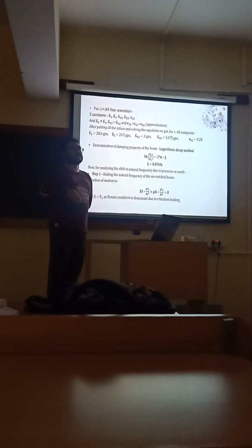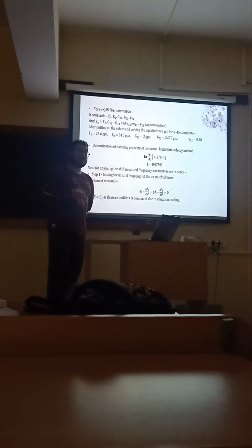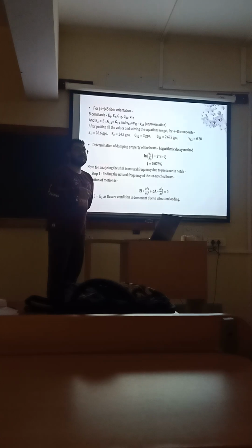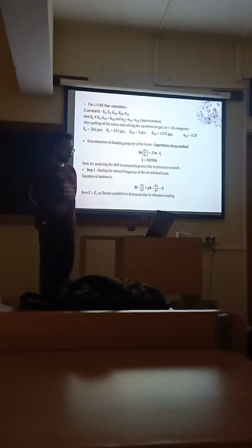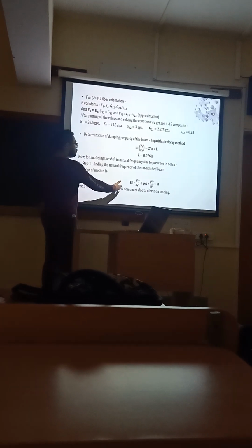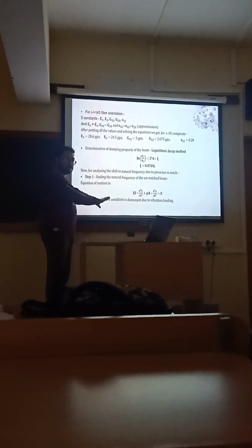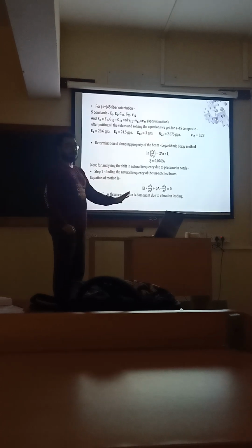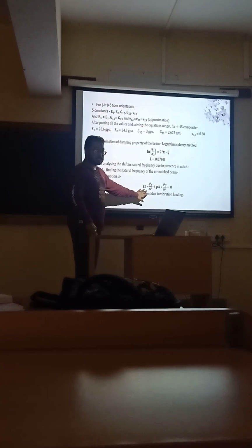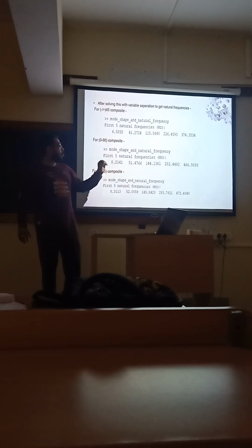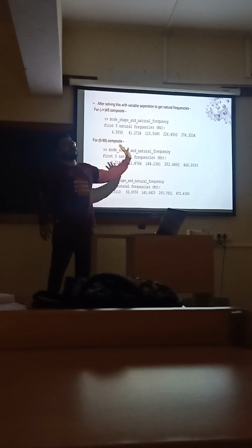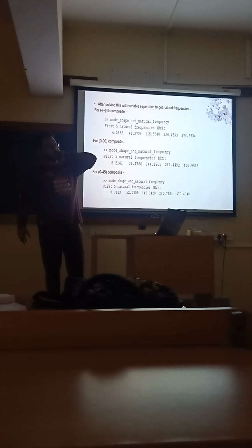Now let's proceed to the second part, where we apply the load and find the eigenvalues, which will give us the natural frequencies. This is the fourth order eigenvalue equation, considering the dynamic loading. This will give us the natural frequencies. I have considered only the first 5 natural frequencies with a focus on higher modes. Now why have I focused on higher modes?